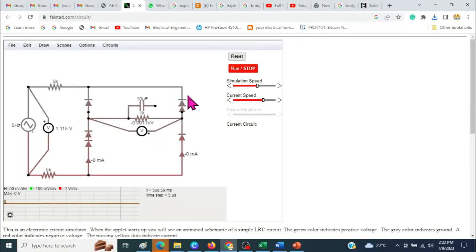So the same here. What will happen technically is that only this diode and this path will conduct, because in the forward bias case, this will quickly turn on at 0.65, and similarly this at 0.6, and this at 0.6.